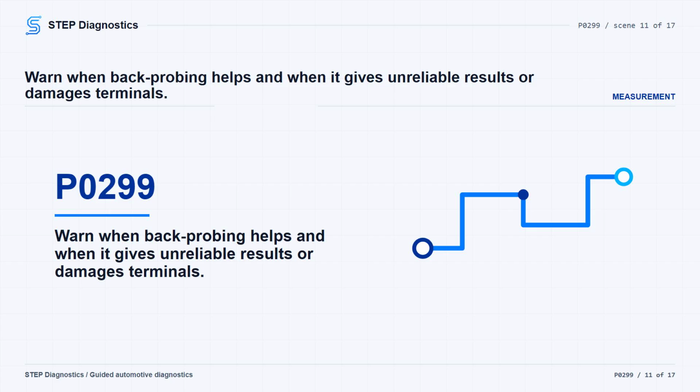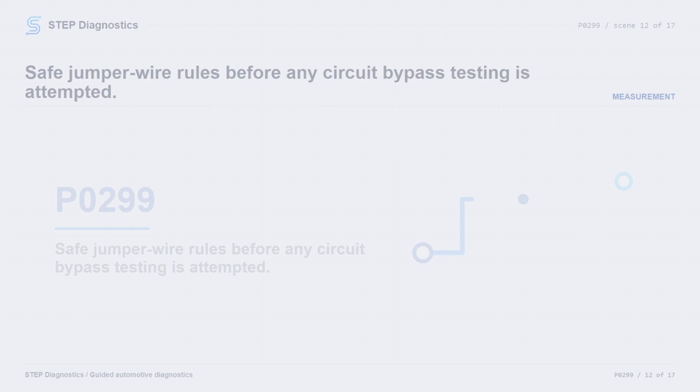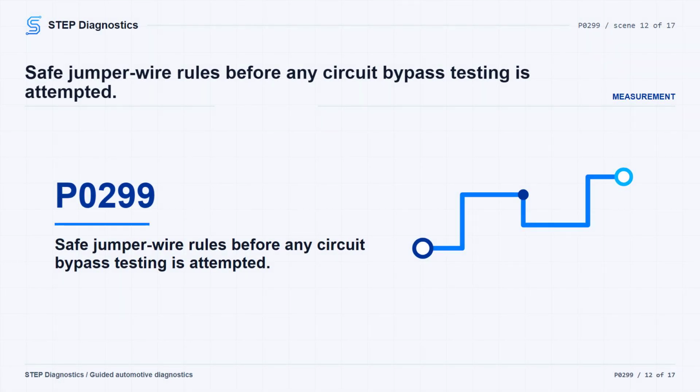A 0-volt result usually means the test conditions are wrong, current is not flowing, or the back probe connection is bad. If jumper wires are used for circuit analysis, always use fused jumper wires. The recommended universal testing jumper wire fuse is 5 amperes or less. Use a larger fuse rating only when the load requires it.